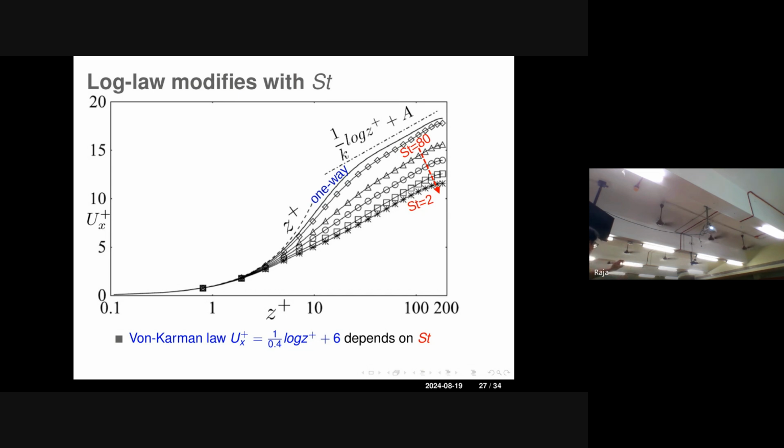So the smallest turbulent structure is of one unit, let us assume. Your particle is of size two. That means this philosophical question comes: I am pretending maybe 2, even though the particle is way bigger. In that case, the turbulent structure you are resolving is 1, but the particle is way bigger than that. That means when the particle is moving, can't it generate additional high frequency structures around it? If that argument really comes in, the entire Lagrangian method really fails, at least the point particle kind of thing.